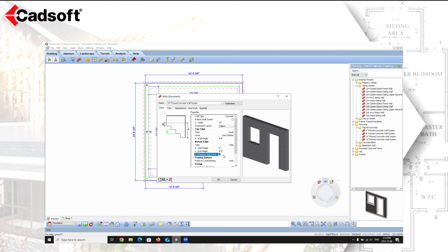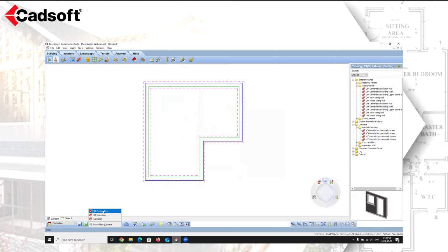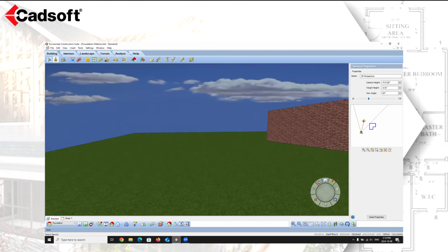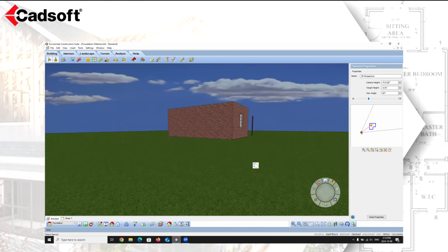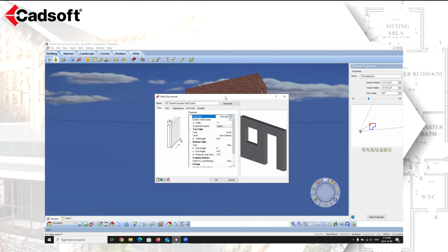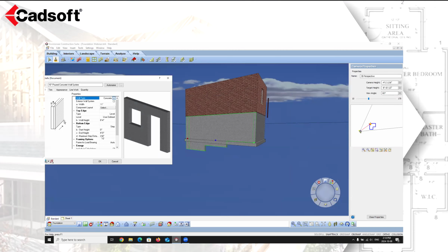And then we're going to go in and our max distance we're going to say is going to be 2 feet. So what we are essentially doing here is we're taking that wall. And if I bring this camera around here to this side, and I pull the camera down, we are taking that wall and we're leaving that first point at 0, but we're dropping it down 4 feet. I'm then telling it that the maximum height that I want each step to be, and again, I'm just going to bring this up so we can see it, is 2 feet.